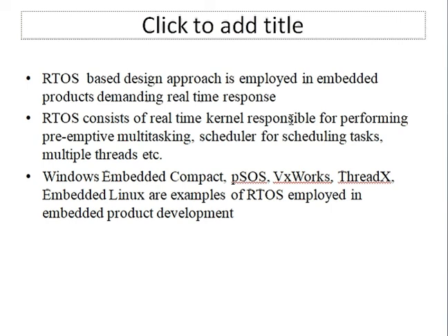As soon as you press a button in that system, the brake has to be triggered. So there, time is the one thing that is critical. In that case, you can use an RTOS, a real-time operating system, when you have multiple interrupts, with scheduling and multitasking services embedded in it, and using these services it can smoothly operate your system.